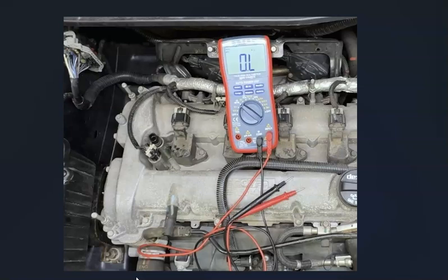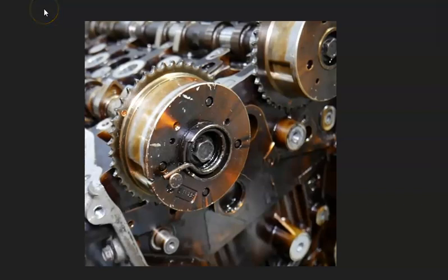The next thing that could cause this is that the actuator, sometimes called a phaser, has gone bad, or there's some kind of issue going on with it. There are some different tests you could do on these actuators or phasers to check them out and see what's going on. There are some good YouTube videos on that. These actuators or phasers are what the timing belt or timing chain is riding on. And the oil is flowing through those solenoids up to these actuators. This is where the engine timing gets adjusted. So if there's any issue with that actuator or phaser, then that's going to cause problems. And so the last thing on the list is going to be a bad actuator or phaser.